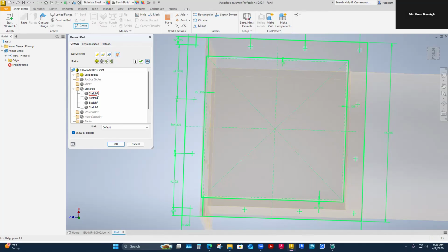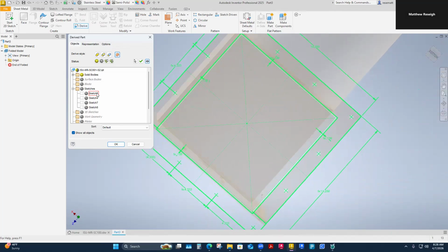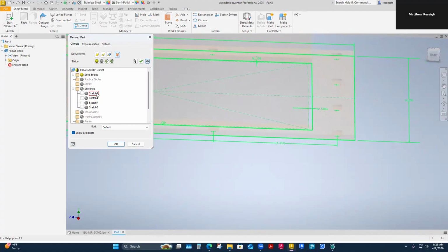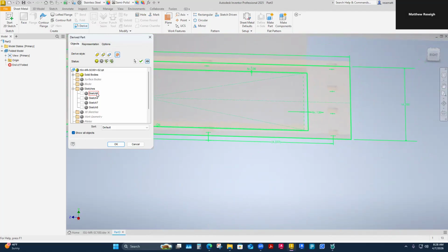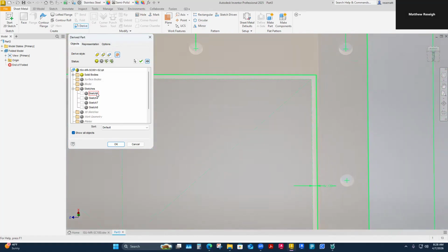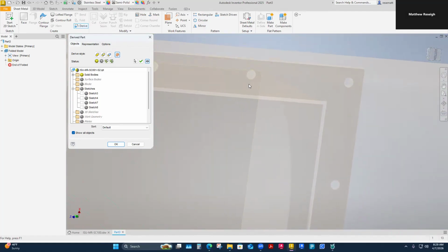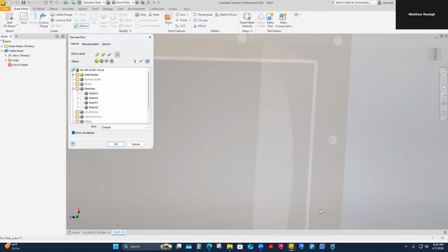You put 875. Yeah. That might be the center. I don't know what the center actually is, but yeah. Like flanges and holes, a lot of times they are centered. Sometimes they are not, because when I put the hardware in, it's easier if they're a little bit further away from the object. That's one thing. The other thing is it allows me, this is part of the assembly process, to think of like a gasket going in here, like a lot of flange connections may have a gasket in them.